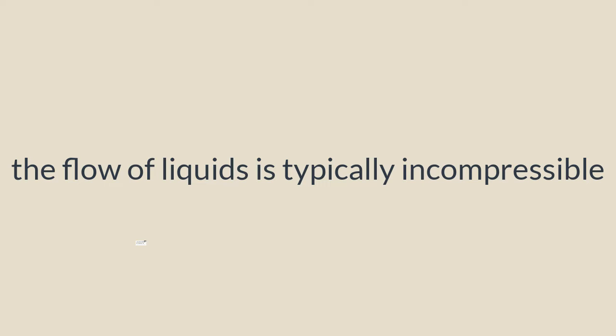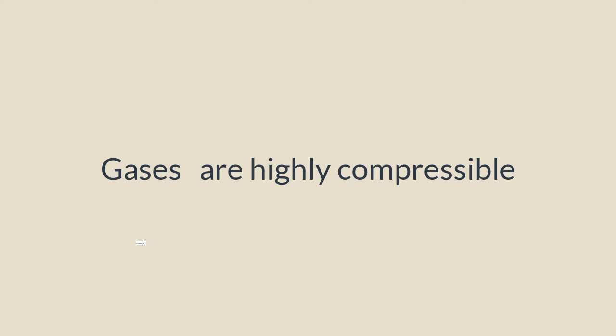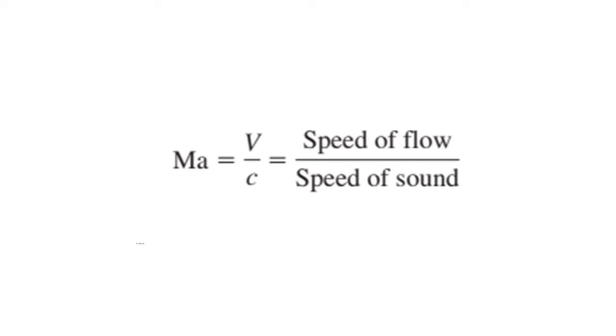A pressure of 210 atm, for example, causes the density of liquid water at 1 atm to change by just 1%. Gases, on the other hand, are highly compressible. A pressure change of just 0.01 atm, for example, causes a change of 1% in the density of atmospheric air. When analyzing rockets, spacecraft, and other systems that involve high-speed gas flows, the flow speed is often expressed in terms of the dimensionless Mach number, where c is the speed of sound, whose value is 346 meters per second in air at room temperature at sea level.